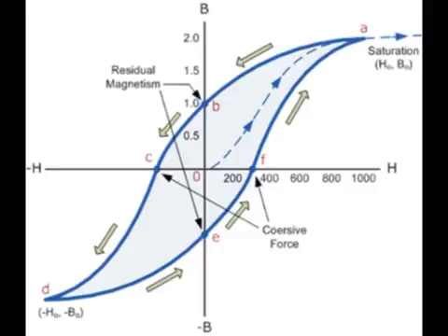In magnetized materials, a form of heating occurs in what is known as hysteresis. In this image, the arrows show how the magnetic field strength H and the magnetic flux density B vary as a current alternates through two cycles. Because dipoles are becoming magnetized in different directions, depending on the current passing through them, they generate frictional heat. Because these dipoles like to hold their position past the time that the current alternates through half a cycle, this residual magnetization causes a different starting point on the graph once a full cycle is finished. The area inside the BH curve is directly proportional to the amount of energy lost in the form of heat within the magnetic core.